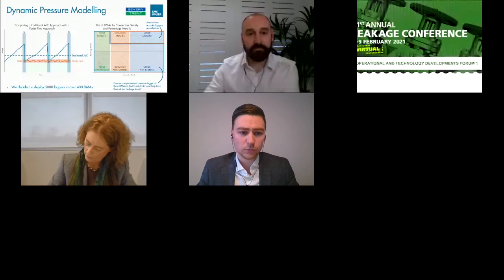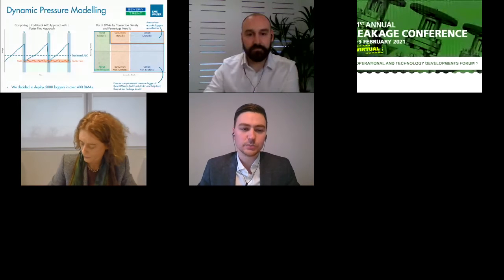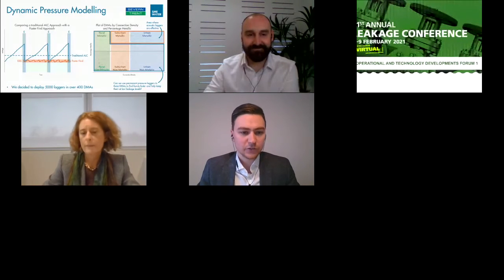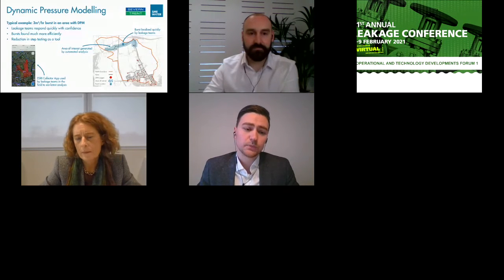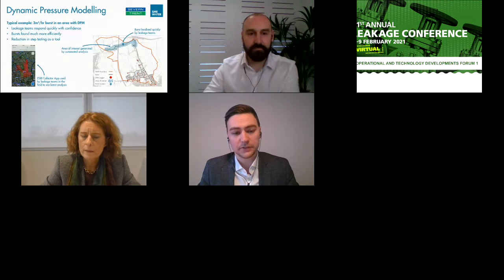So I'm just going to talk about what DPM is in layman's terms and how I understand it, and Stu will go into some of the more detail. But just to give you an idea of what the frontline technicians, the water network techs see and get, a lot of work's gone into this to get to this point, probably 18 months of installation, development, fine-tuning of the algorithms to get to a point where we can start to put this into the front line. So the screenshot on the bottom left is a collector app visualization of what the guys will see now out in the field, and that will start to highlight polygons within the DMA where we believe, if there's a burst, where the likelihood is that the burst has appeared.